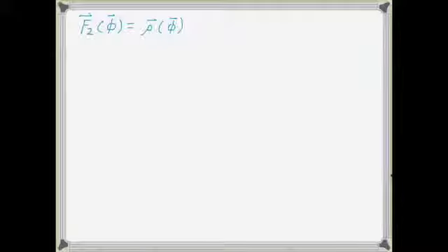So let's go back and look at what rho is. Rho was equal to q times (Nd+ minus Na- plus p minus n). And we said that the way we're doing things, these are just constants, they're not functions of phi. They're just determined by whatever your doping density was. So if I take the derivative, they're just going to disappear.